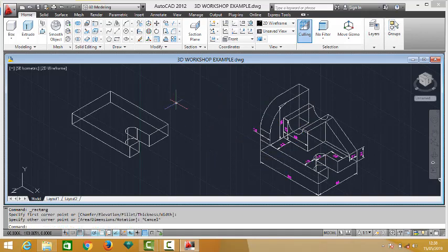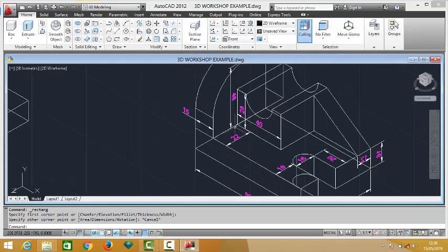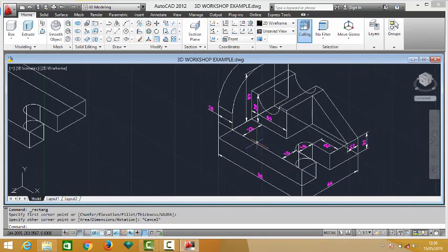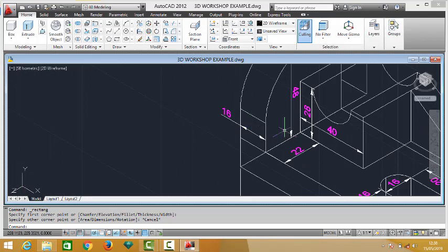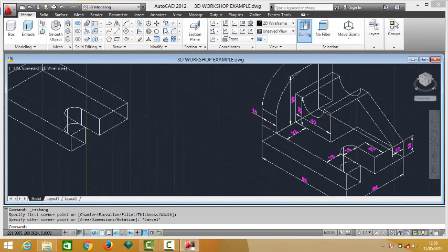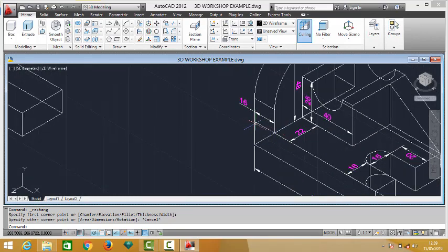Good. So now, for us to do this, we need to use what is called absolute coordinates. Absolute coordinates means typing in X, Y, Z distances. So what we'll do is that we are starting from this point here. We start from this point here, we'll move here 16 and then move here 22 in order to get here.